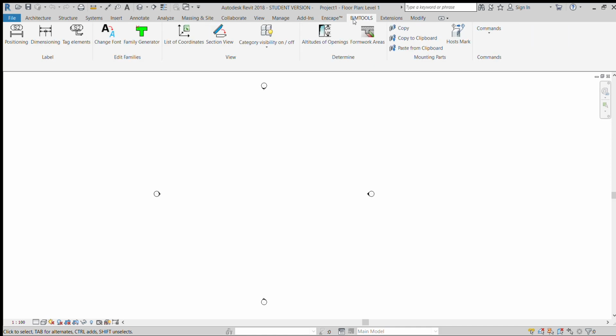Next, BIM Tools. This is an additional plugin for Revit, right? What purpose is this plugin used for? You calculate the centering sheet area for your frame structure. How many centering sheets are needed for my column? Simply click this format and it is calculated, vertical and horizontal also. I simply calculate the centering sheets for my whole framed building: beam, column, slab, all of them in my framework.